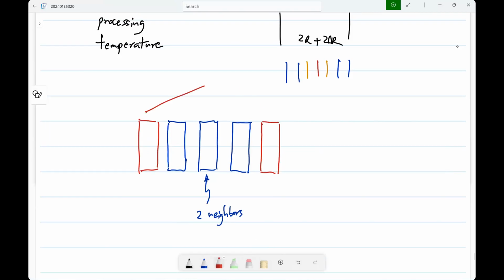These are called dummy devices. This is just to make sure that the physical environment is the same for all elements. And you can have one or more. I mean, more may be required in some cases. Basically, you have to waste some area so that all the elements in the center are identical to each other. Again, I'm showing examples of resistors, but this is true for any element.